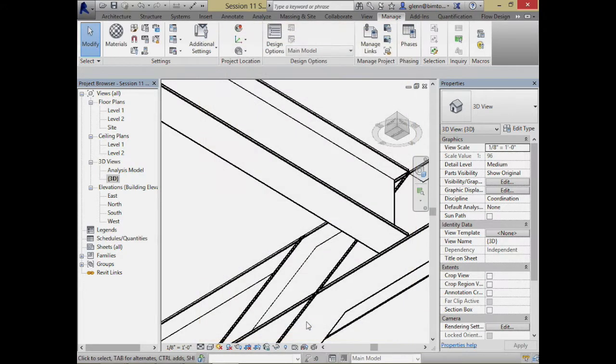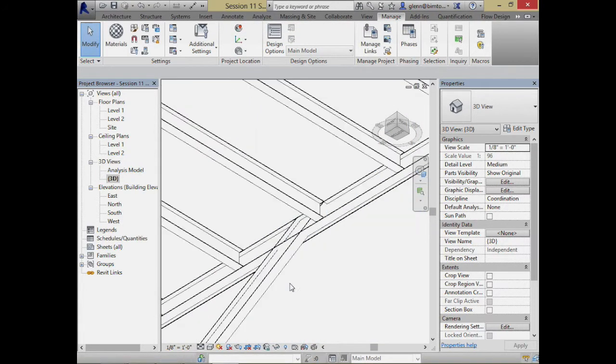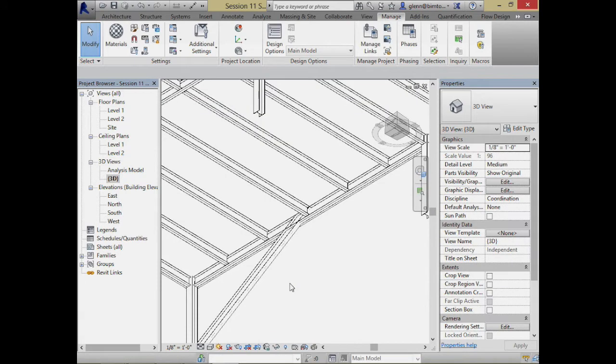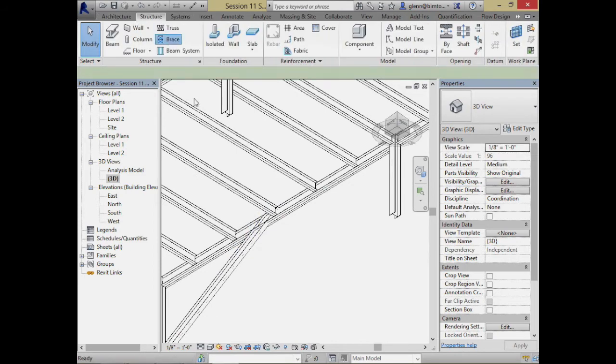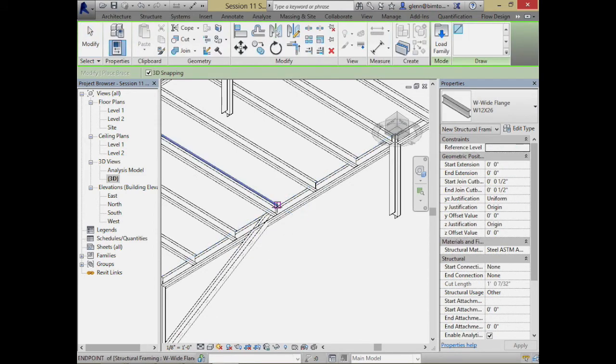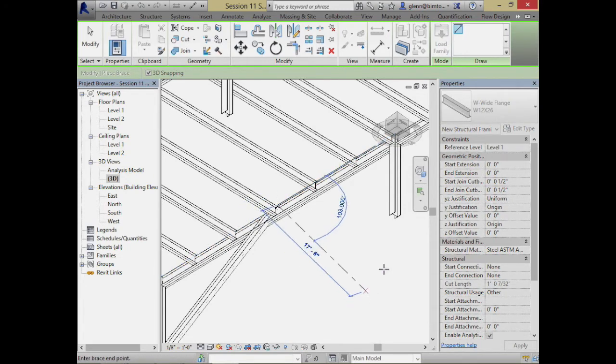So if I'm over here and I say SM, typing that, I should be able to get more to the midpoints of objects. So that should help me in terms of, let me go back to the bracing. That's an endpoint, SM. That's actually the midpoint. It's interesting. I'm not even on the midpoint, but it's snapping to the midpoint. You see that? It's over there.